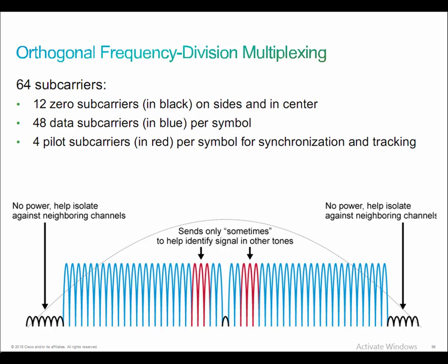So it is 64 subcarriers, and that's the 52 plus 12. If you do the counting here, you can see what each one of those represent. We have the sideband channels, and then we have the carriers in the middle.